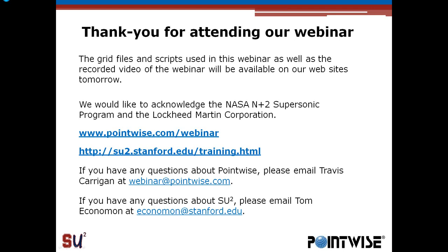I see. I can go ahead and take that one. So yep, inside of SU2, the Python script that I showed you calling shapeoptimization.py is going to call the SLSQP optimizer inside of the SciPy package, which is just one of the packages you can download for Python. It's a scientific application package, and they have some optimizers available in there. So we can do constrained optimization problems using SLSQP.